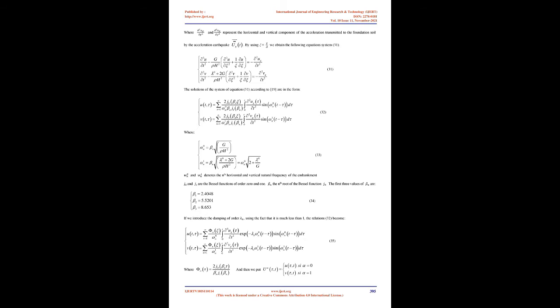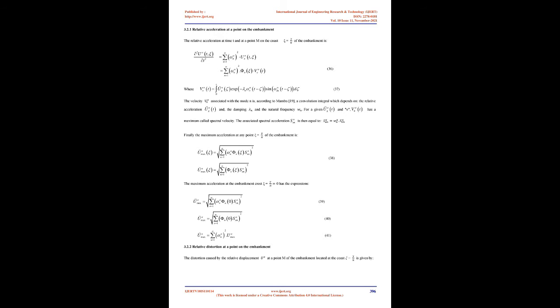1. The material of the embankment body is homogeneous and its mechanical behavior is governed by a linear elastic law. 2. The influence of stored water is negligible, no significant loss of strength in relation to the generation of pore pressures. 3. The embankment is infinitely long and modeled by an infinite number of thin horizontal slices interconnected by an elastic spring system. 4. The mechanical problem considered is the planar type, where rho, G, and lambda are the density, shear modulus, and Lame coefficient of the embankment material.